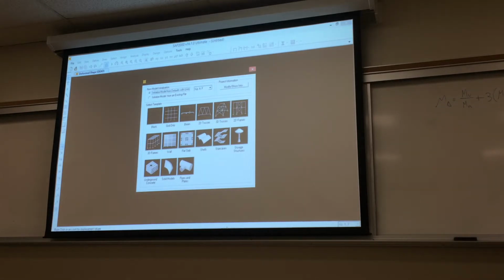So I'm just going to start from the basics in SAP. I know I've jumped around a little bit with it so far, but I want to go from the ground up. We're going to build the model. I basically want to solve your homework problem in SAP, but we'll also verify different steps as we go along. You can check to see you're correct if you're moving from push to push. So SAP has a lot of defaults you can use. I'm just going to do a 2D frame, starting in units of kips, feet, and Fahrenheit.